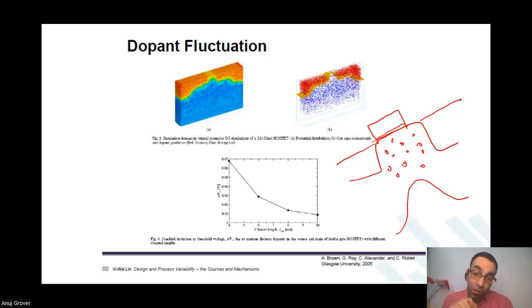Yes, sir. You're not placing dopants one by one. You're just bombarding and you're letting them diffuse. There are bound to be variations. But the machinery which I'm bombarding with, I have the frequency, everything in control, right? So I can be sure how much I'm bombarding.